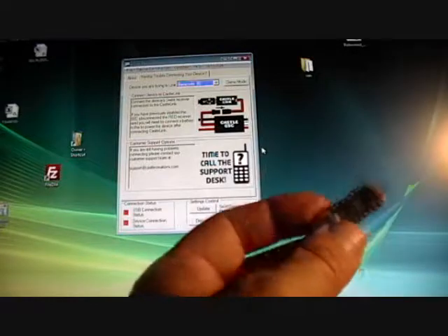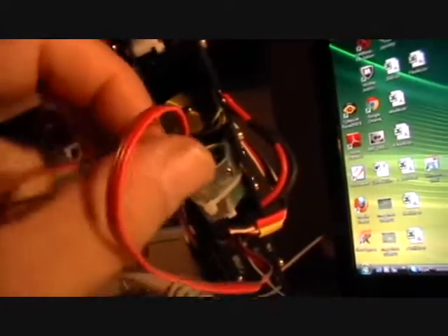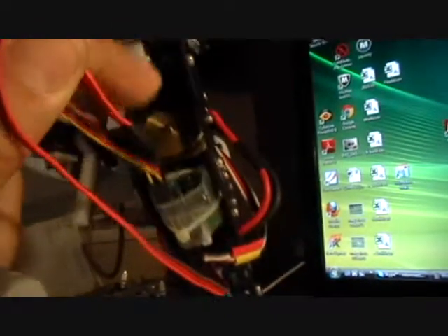So you can actually just send that coupon in. They'll send you one of these Castle Links. You just plug that into a USB. You pull the speed control controller wire, unplug it off the nacelle wiring board, and just plug it into the Castle Link, making sure the polarity is correct.